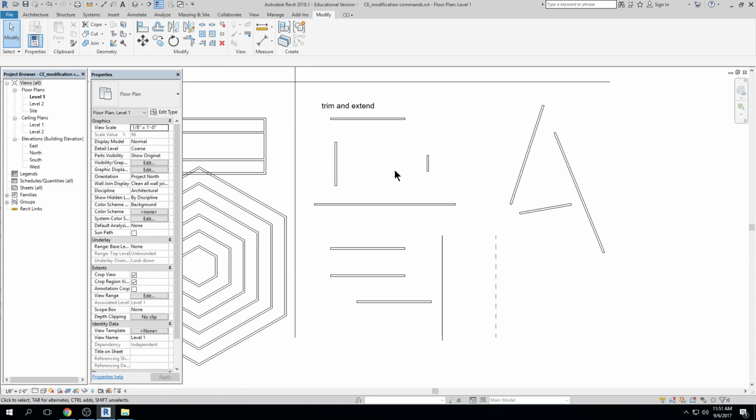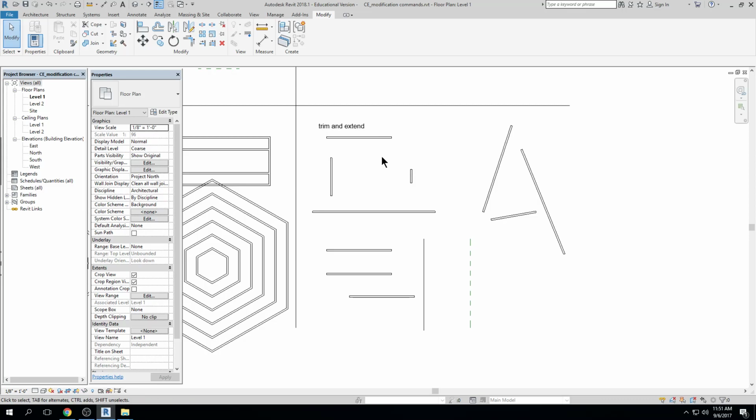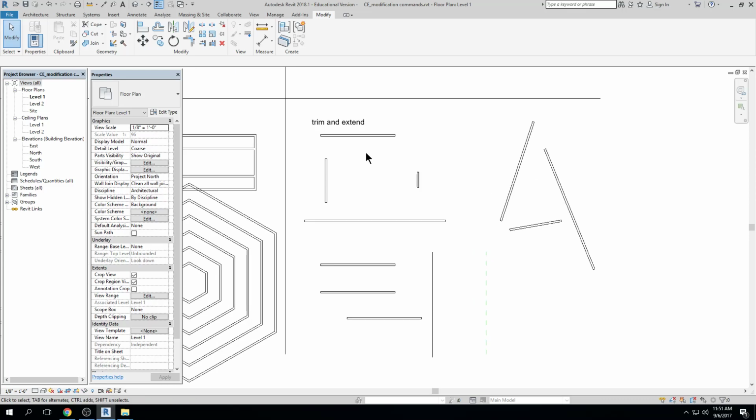And finally today, we've got 5 minutes to finish trim and extend, all right? In AutoCAD, when you are creating squared off corners, you use fillet with a 0 radius, and that will give you a great squared off corner. You can also extend an object and then extend a second object to that object and then trim off the excess to create a squared corner, right?